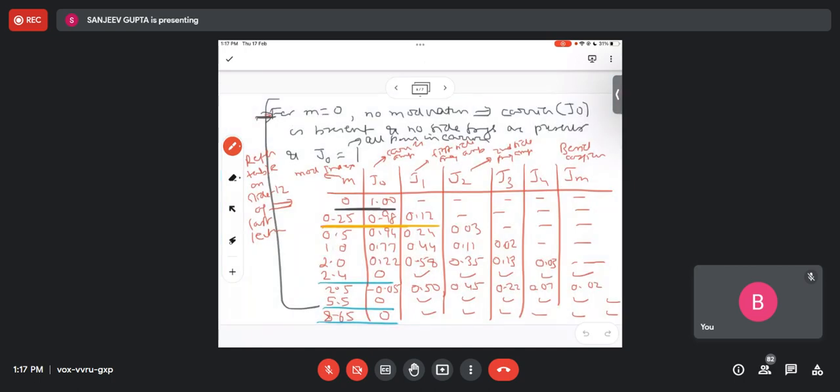Whenever a problem is given, you will be provided with these tables. So no need to mug up the table or the equation, but just to give an idea how a Bessel function can be used to solve a sine of a sine function, which we encountered in an FM modulated signal. I stop here and we'll continue in the next lecture.